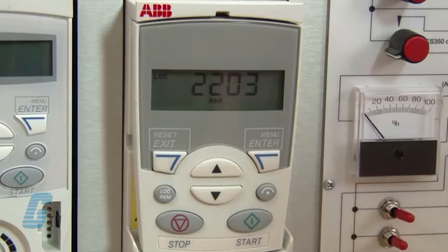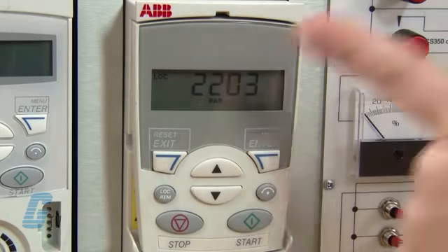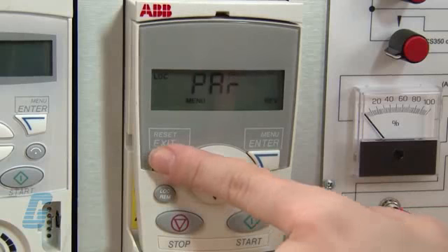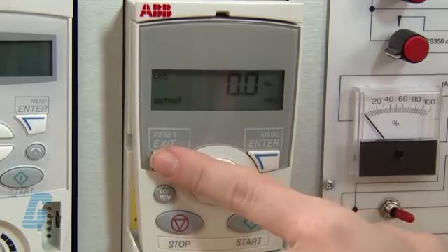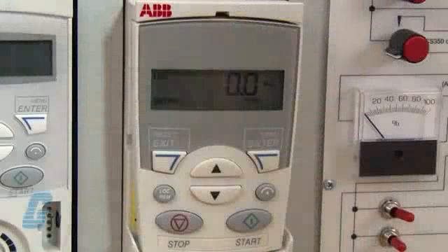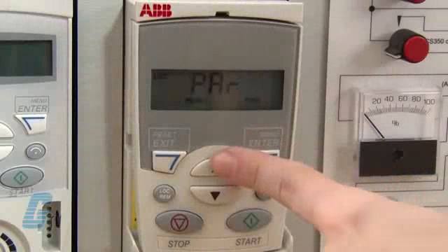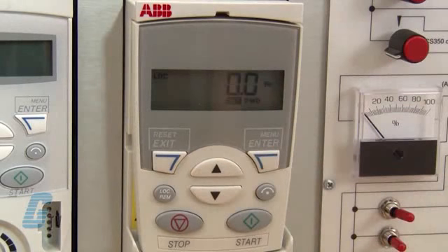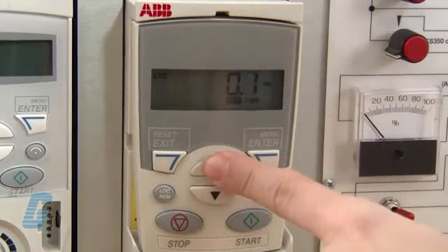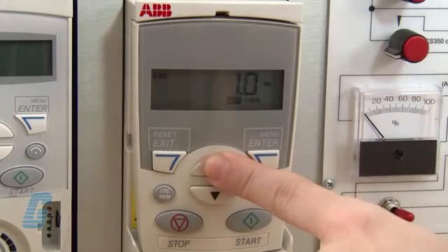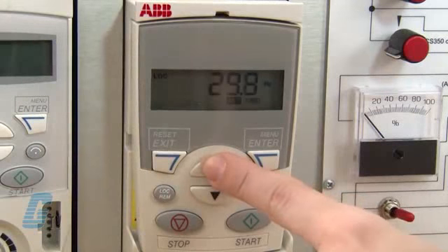Once I am finished adjusting the parameters, I can push the exit key a few times to get back to the output mode. I'll be sure to check that there are no faults or alarms shown on the display and that I am in local operation before I start the motor. Now I'll go into the reference mode by pushing the menu key and then scroll to REF and press the enter key. I can now push the up arrow for my desired speed and then push the start button.